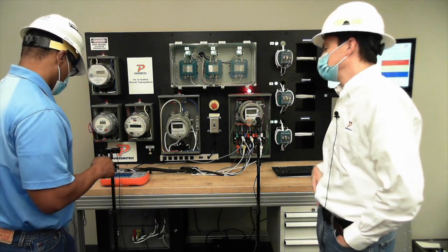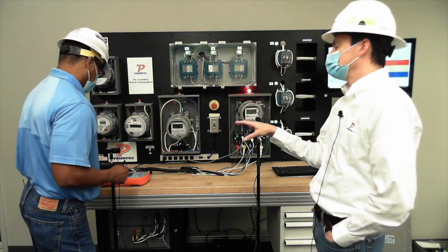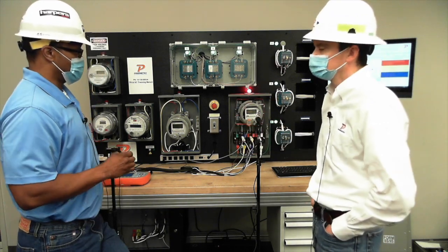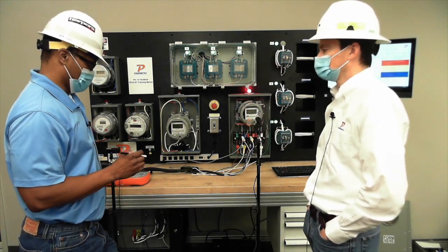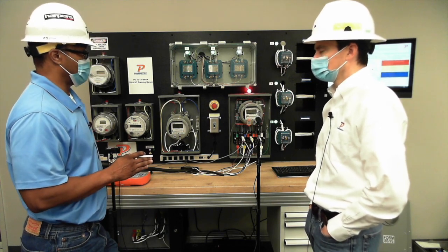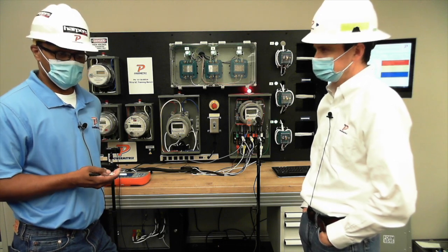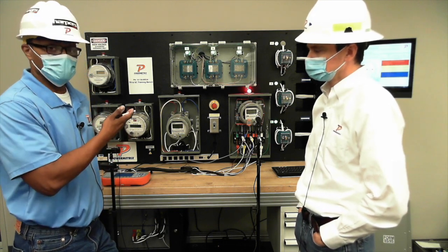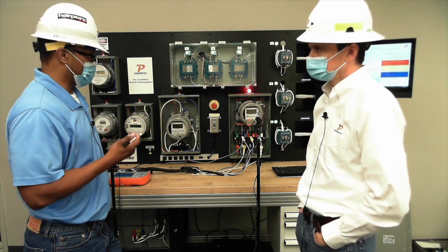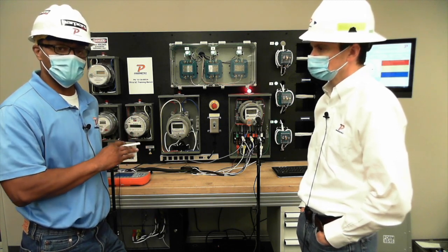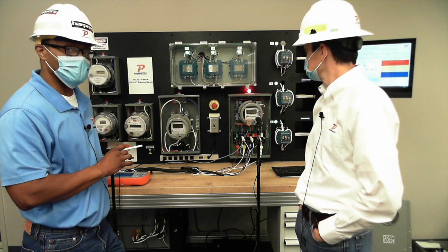Could I use a demand test if I had a load box? If I had a 335 or if I had a 7 series? Yeah, now you can do that. And I've done this a lot of times. Let's say you get out there, they want you to go out and test the demand using a 7 series, and you get out there, there's no load on the meter. So again, the first thing I would do is write down the kilowatt hours and the kW, everything that I'm looking at before I've touched that meter.